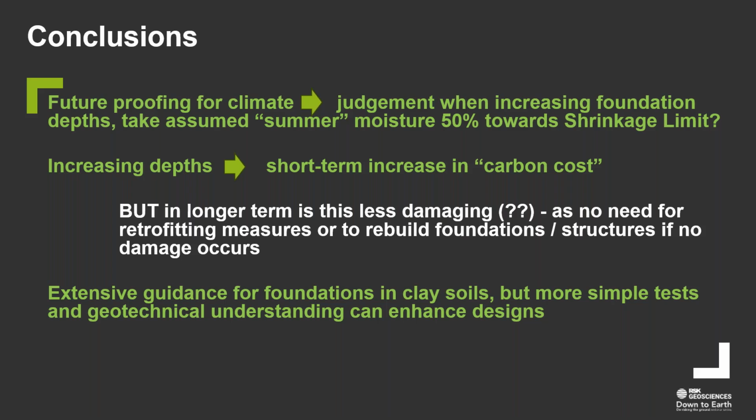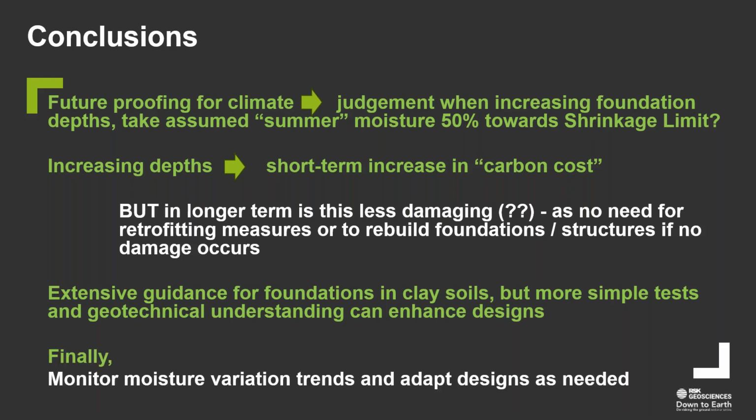Years ago, I remember a site where there was an orchard of cherry trees, and the trees were culled before a winter period, and then moisture content depth profiling was done, and then after about 9 months it was revisited, and the zone had actually reduced, and therefore there was a reduction in the economic foundation depth. So there are ways in which simple designs and just testing what is your actual soil moisture content now will generate an improvement in the overall design cost.